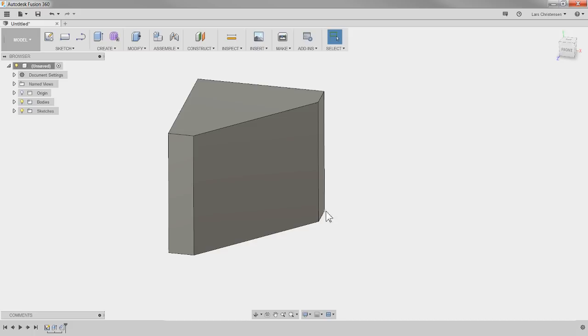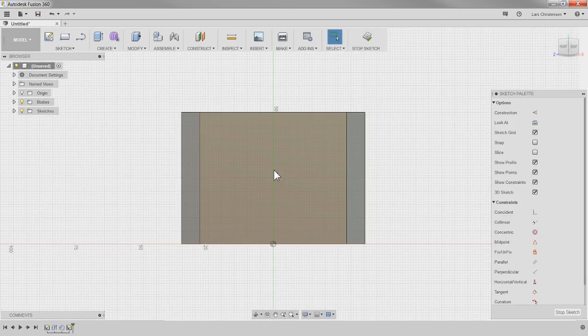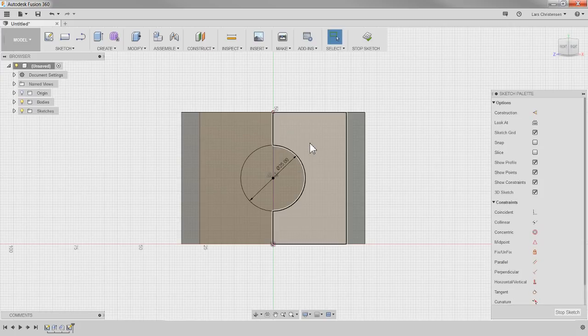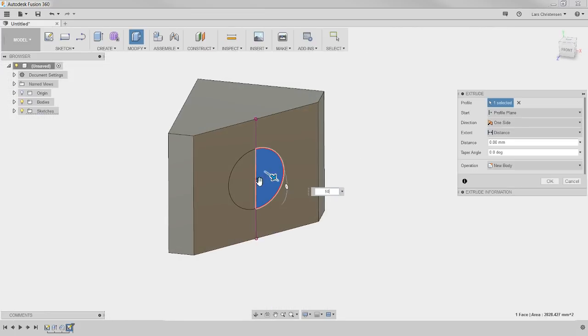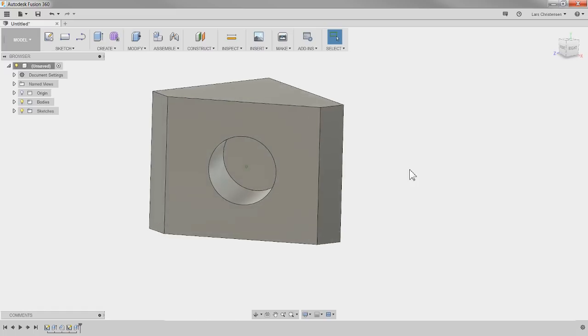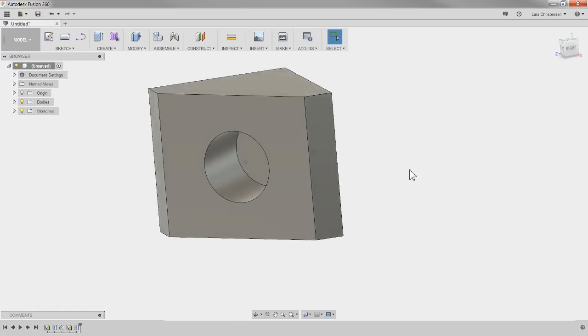All right, now while we're on this face here, I'm just going to open another sketch, do C for circle, and actually I thought I could snap into something here. There we go, center point, 25 diameter, this doesn't really matter. Let's extrude some depth to this one, minus 25. Okay, so that's what we ended up with. Something that looks like this.